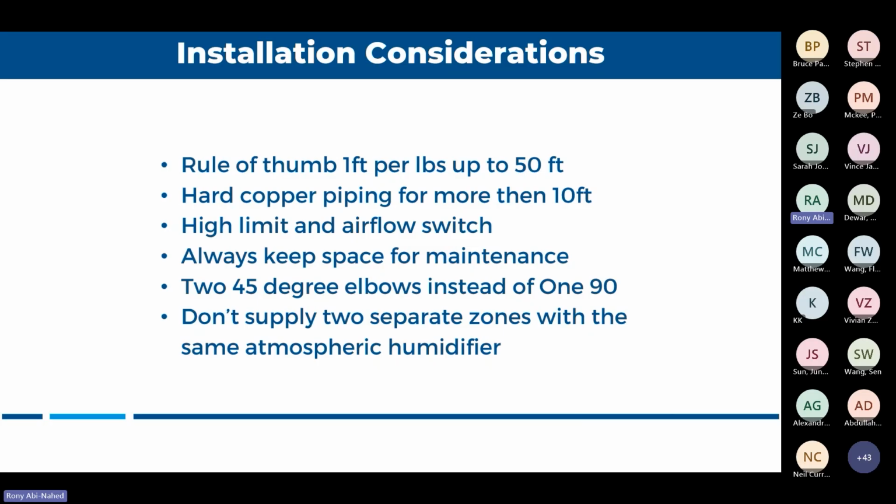So anytime you have more than 5% difference, you are at full blast. Between 95% and 100% of what you need, you're modulating the unit to maintain your capacity.